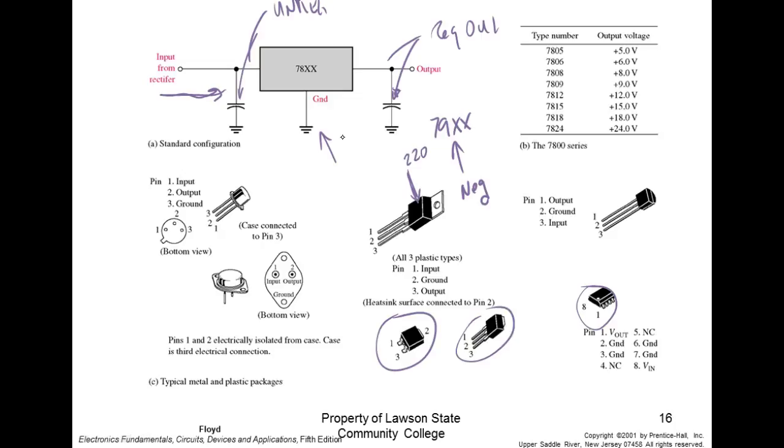Really? So think about it. Okay, I need a 1 amp power supply, 5 volts. I try to get a 6.3 transformer, 1 amp. Then I would make sure my transformer can handle 1 amp right on the output. Calculate my ripple frequency, my ripple, and the size capacitor I need, to make sure that when I'm pulling my maximum current, it doesn't dip into the regulated voltage. That's pretty much what it is. So these guys are real easy to design.